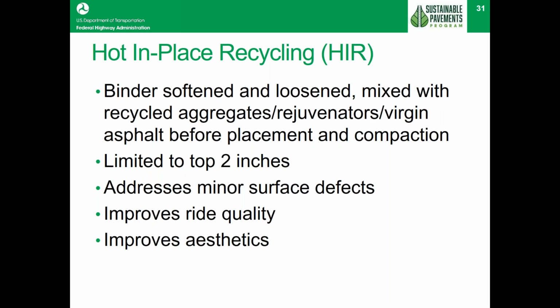Okay, hot in place recycling. This is one of those activities that's not done a whole lot around the country, but we do find it very popular in certain areas, particularly where trucking is a really big issue. It's not necessarily a preservation treatment, but it is valuable in terms of some of the sustainability elements of it. This is basically a case where you're reconstructing the surface from what's already out there and adding a little bit of asphalt material and some other additives to restore that asphalt back to a very good condition.